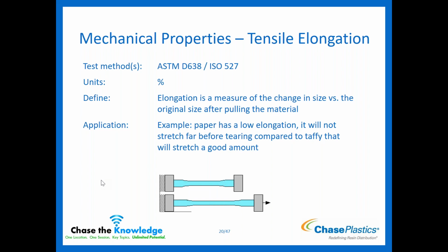If you are looking, again, Ultem 1000, it's done at yield and at break. So there's two very different percentages there. It's only 7% at yield and 60% at break. So again, if you're comparing, just make sure you're looking at the same property and the same condition.